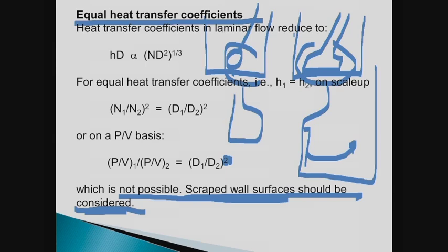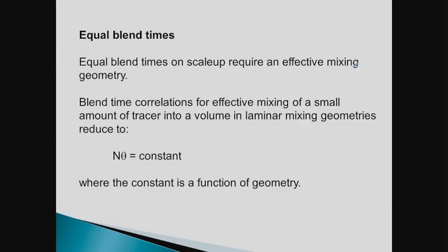Your heat transfer problems go up enormously, and so you have to go with a scraped surface. You turn down the heat, is what you do, so it doesn't burn, and then you go with a scraper, a spatula, rather than just the tip of a spoon.